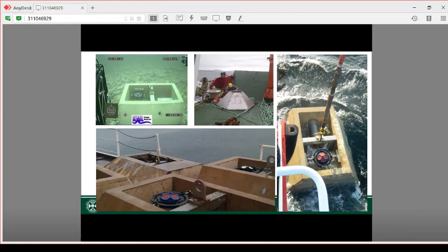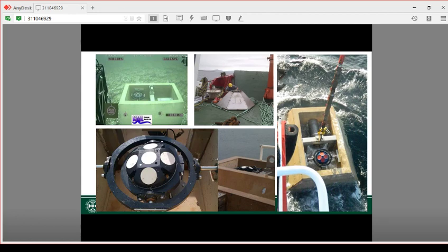Just to give you an example of trying to do this, this is a highly tidal environment. The current flows at 5 or 6 knots, and you've got to put stuff down. So if we're putting down a small ADCP, then we have to embed it in about 2 tons of concrete, otherwise it doesn't stay where we put it. So we've got a lot of concrete frames, you need a lot of work boats, and you'll see that we also mount the devices on gimbals because the floor is not level. So there's ADCP on gimbals.